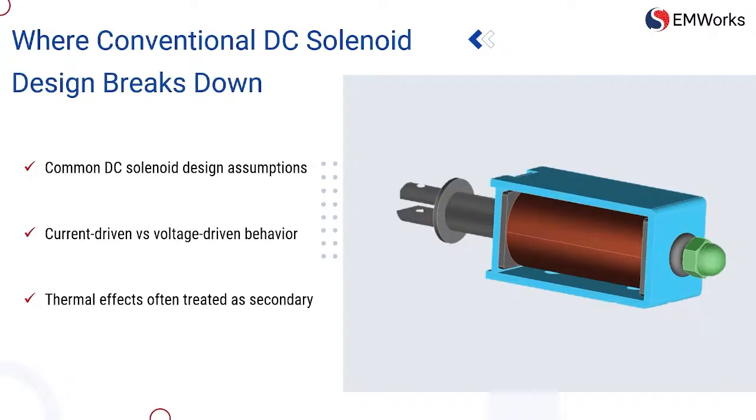The issue is that this mental model does not reflect how most solenoids are actually powered in real applications. In practice, they are voltage driven, not current driven. And once you accept that, the electrical and thermal behavior become inseparable. This is why this topic matters. If the assumptions are wrong from the start, the prototype will reveal it later, often in a costly and frustrating